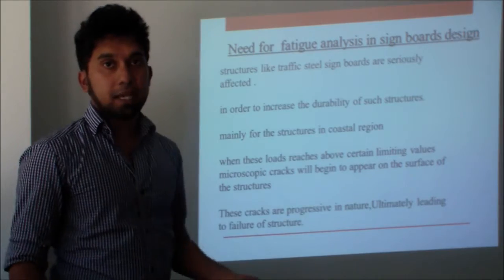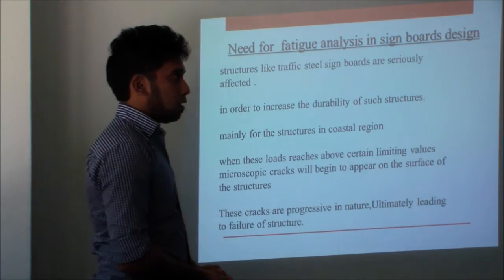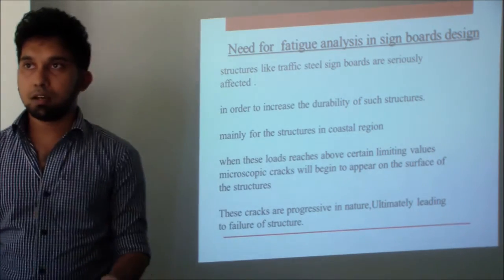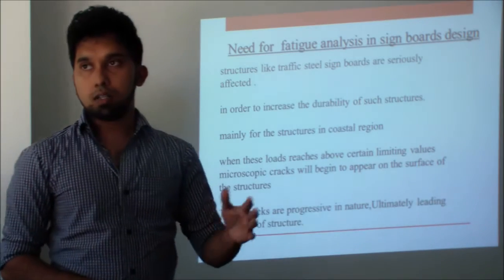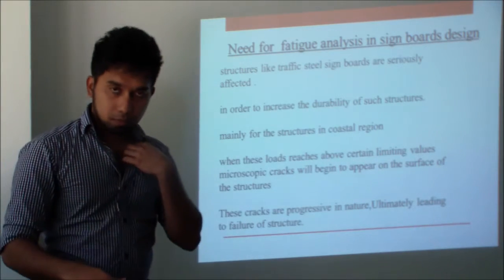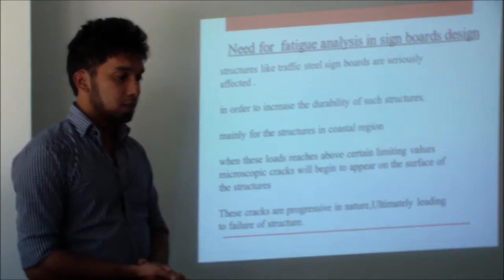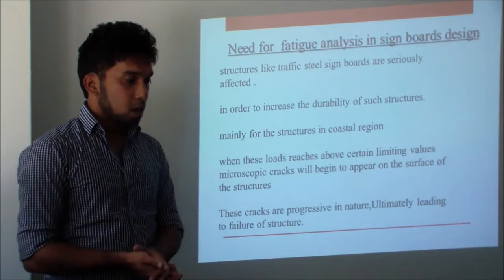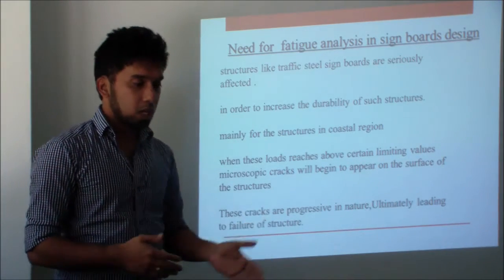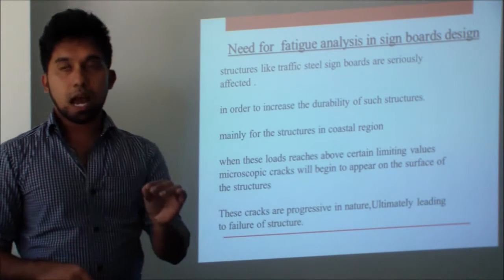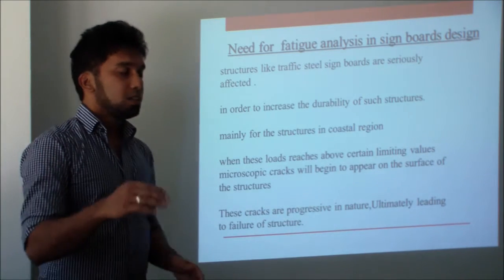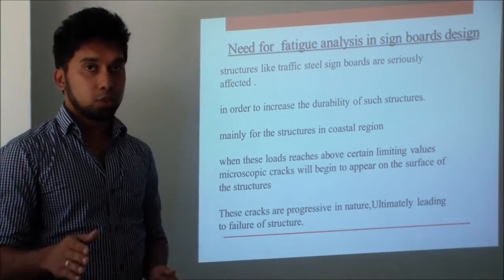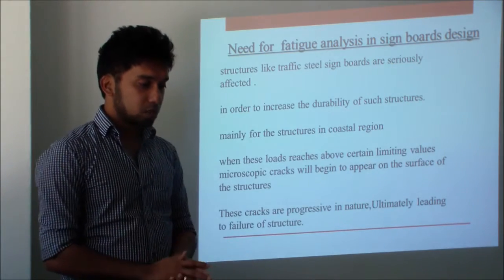So what is the need for fatigue analysis in signboards? Since these traffic signboards are highly affected by wind forces, when we take a drive, we can often see the signboards torn out due to wind forces. In order to increase the durability of these structures, there is a need for fatigue analysis. When the load reaches a certain limiting value, microscopic cracks will form on the surface of the signboards, which will progress with time and finally lead to the damage of the structure.